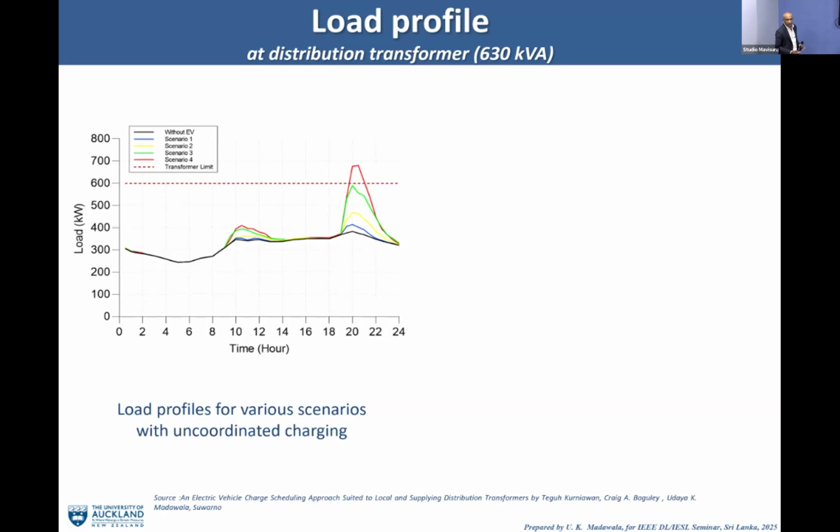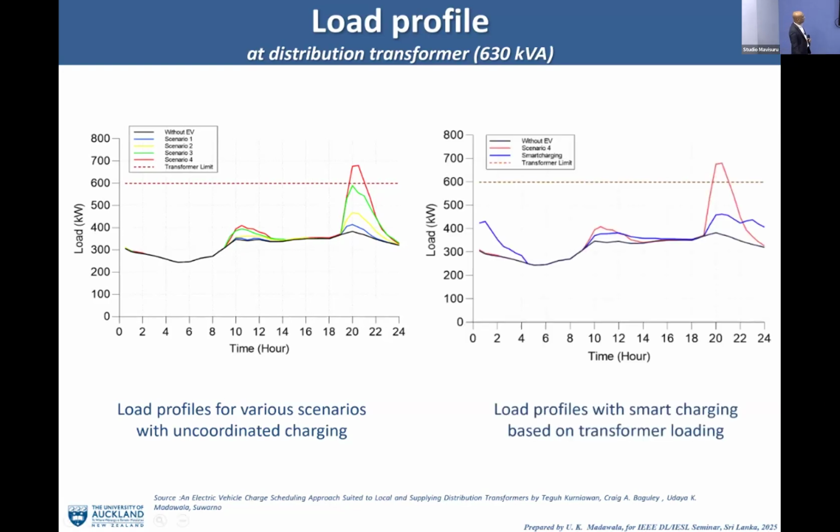You can replace the transformer very quickly. But even if you replace the transformer, you can see it's not needed during that period, so it's no problem. So what we can do is the smart charging, what I showed before. There you can see the worst case scenario is still well below the capability of the transformer.